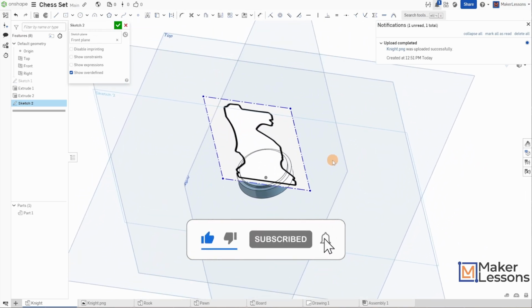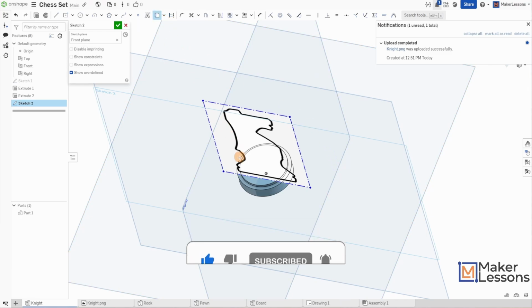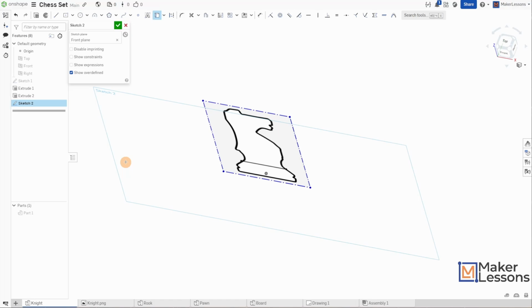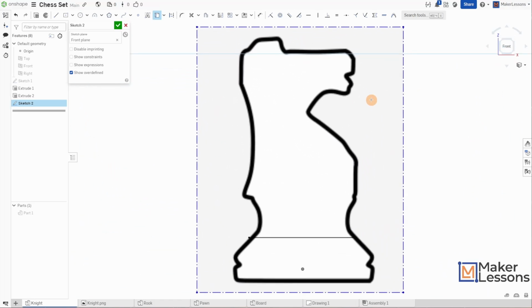Now, what am I going to use to trace it? Well, let me do that use button real quick here on the base. So I have the line, and I'm going to turn that off, turn my planes off. Let's get to actually looking at the direction I'm drawing in. So to trace this, I'm going to use a spline line. So I'm clicking on that. I did my use button. I'm a little off on the edges. It's really going to be okay.